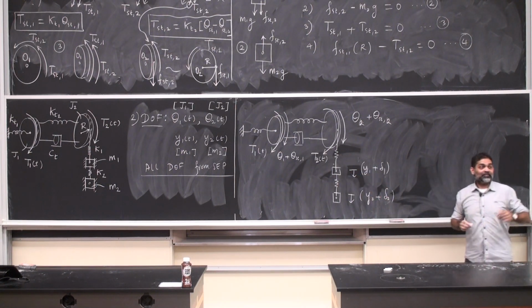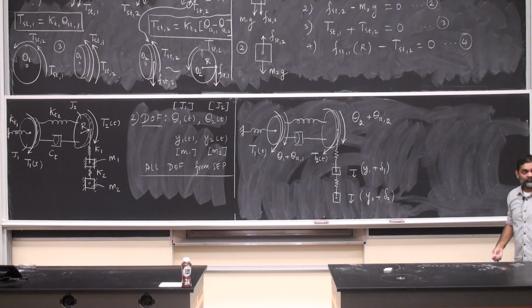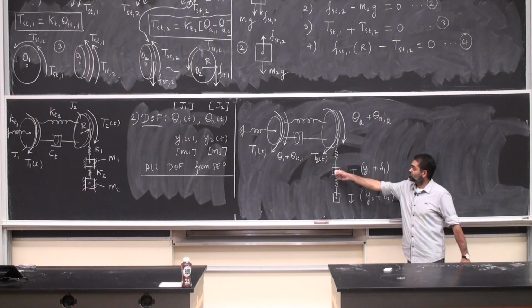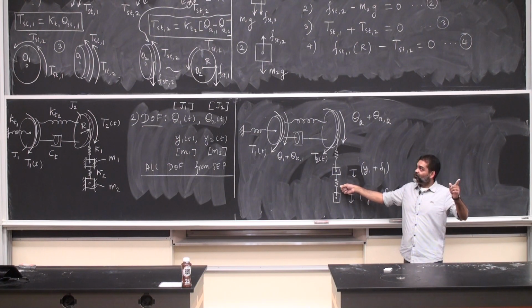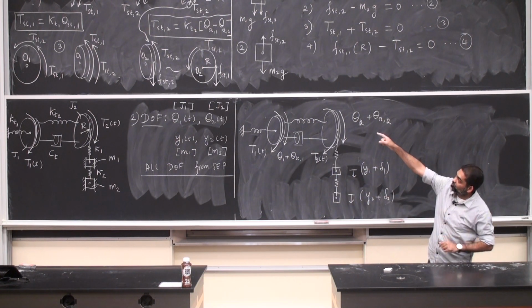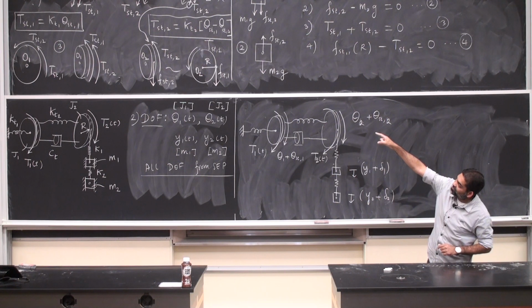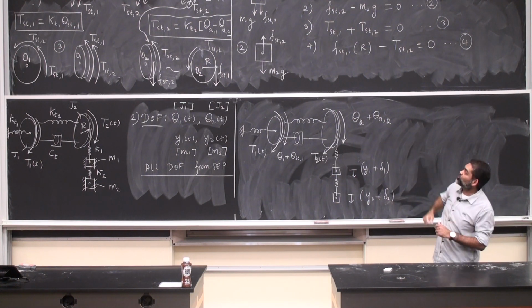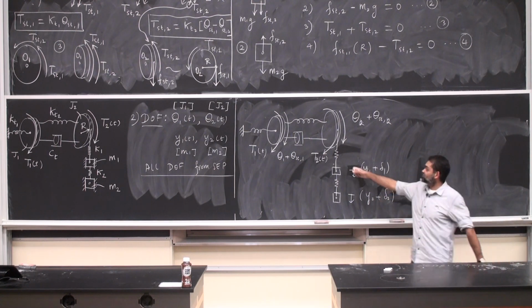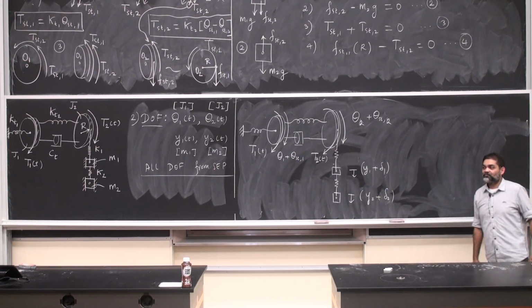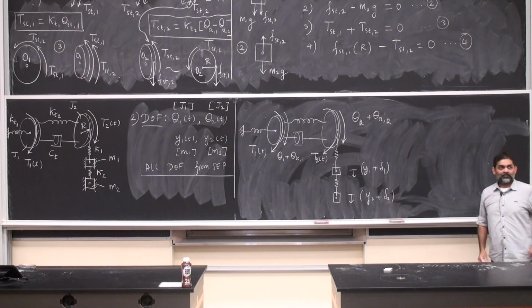What would happen there? Yes? No, because a damper can't support weight. It cannot support weight, but you see the weight of this could be supported by this spring. But not the whole system. But you see the problem, what you're referring to is the T static 2. That would no longer be there, you see. So it is completely fine if I replace this by a damper. Does everybody see that?